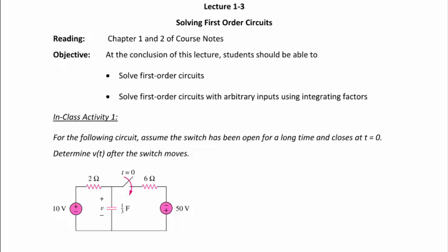We will continue our analysis of solving first order circuits which have a step input such as a u of t, but we will also look at circuits that have arbitrary inputs using integrating factors. We will also analyze circuits which have switches or step functions as well, because as we talked about in lecture 1-2, a step function is a way of representing a switch opening or closing on a circuit.